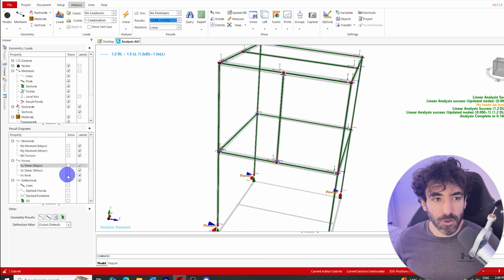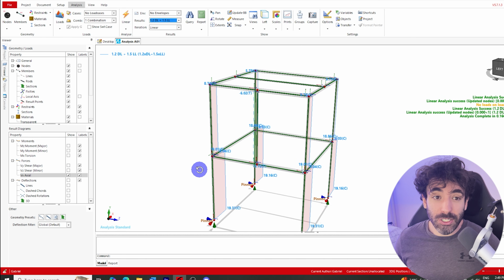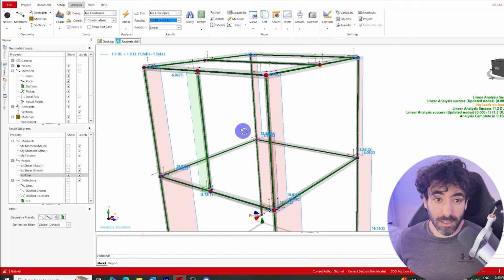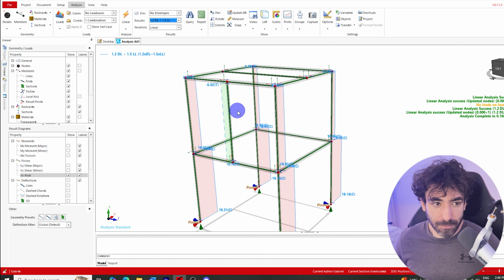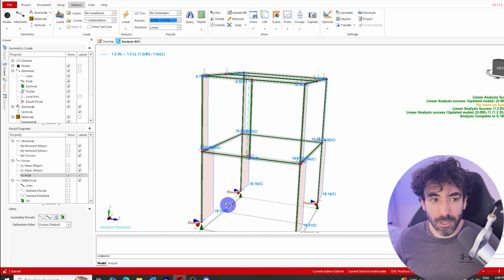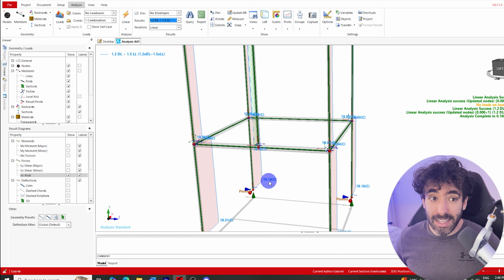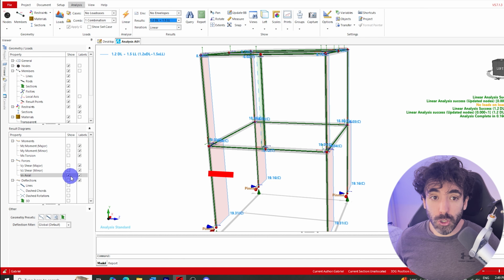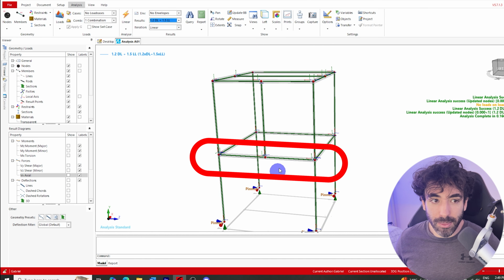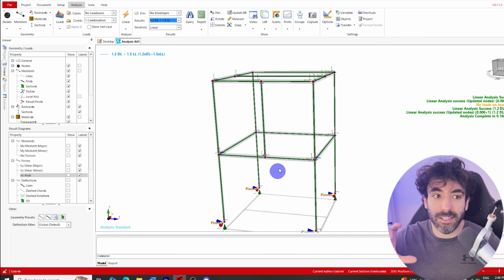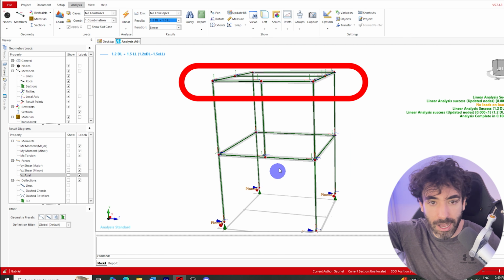If I look at the axial force diagram, we can see that this column is in tension. Therefore, it's supporting this beam. It's not loading the beam. So what's my point? That yes, you might use a smaller beam underneath, because maybe the architecture design intent didn't allow for much space in the floor framing, and there's a greater clearance in the roof framing, so I will use a larger section up in the roof framing and a smaller section in the floor framing hanging off this column.